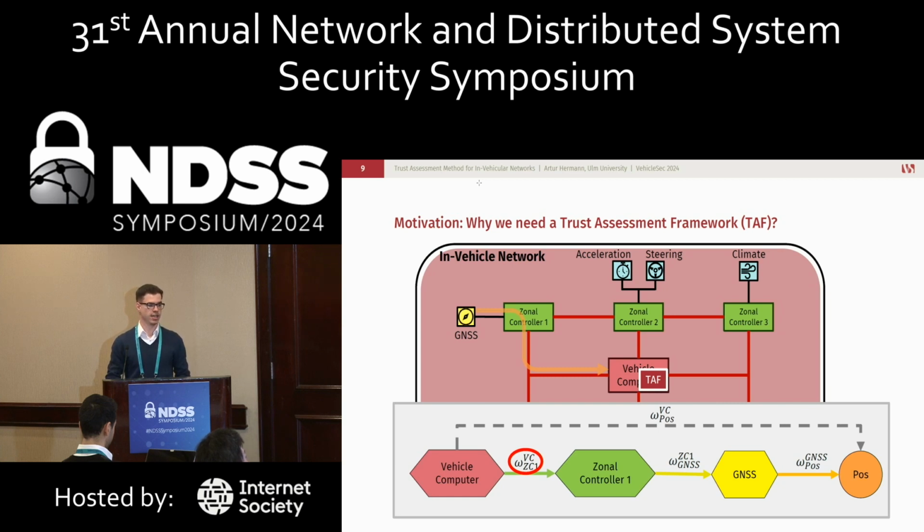And here, many different aspects can be taken into account. We used the implemented security controls, which are implemented in the zonal controller, because depending on the implemented security controls, the risk of the ECU being compromised would differ, and therefore this should be taken into account when it comes to the trust assessment of the ECU.